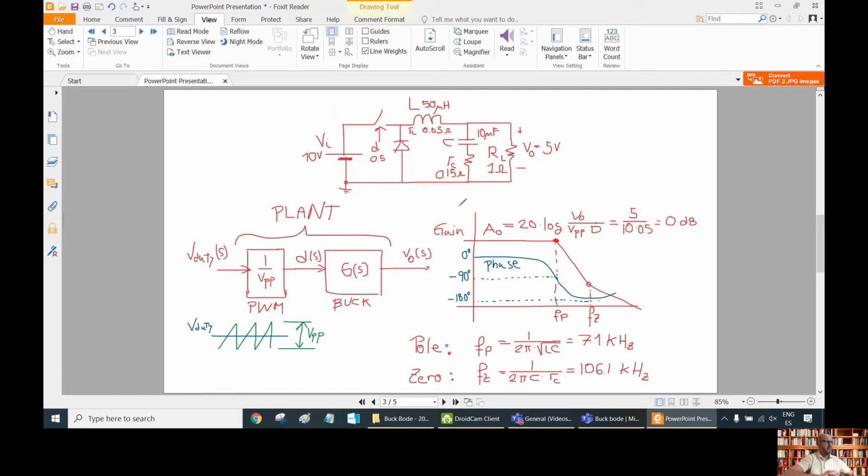So we know that the buck converter behaves like a second order circuit with a second order frequency response. We are going to consider only the buck converter operating in continuous conduction mode. So we know that the response of our converter is going to be like this. This would be the plant. We are controlling the duty cycle of our switch using this signal, the duty.